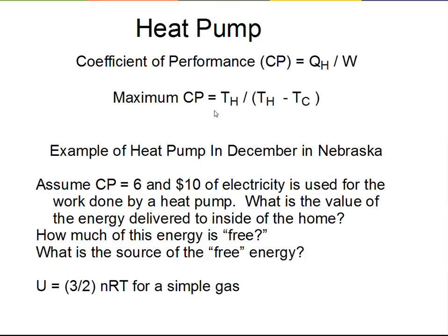If you're using a groundwater system, then you don't have to worry quite so much. The air temperature is very variable through the winter months. A groundwater system, this T sub C is more reliable and a steady value and not as cold as the air because it's still liquid water. It's not below 0 Celsius.